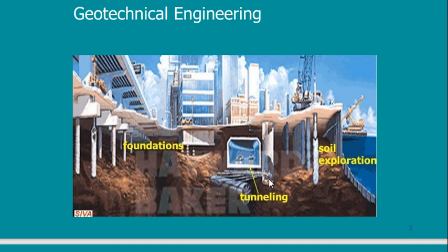Yes, of course. If the soil formation is different, we know that below the Suez Canal, we have many tunnels. Are all tunnels the same? No. Some tunnels are in Port Said. The soil there is very, very soft. And some tunnels are in Ismailia, where the soil is very good. So this tunnel is completely different from that tunnel. The design method and the construction method are completely different. So I need to know what is the type of soil to design my tunnel.